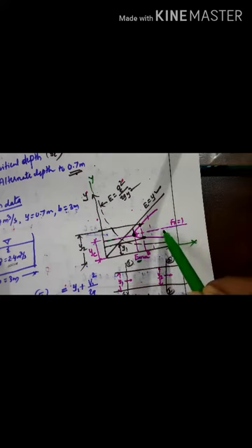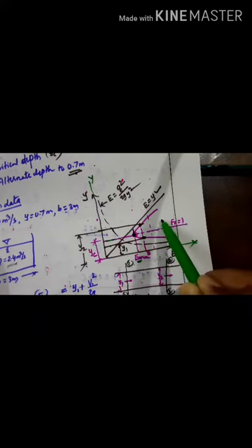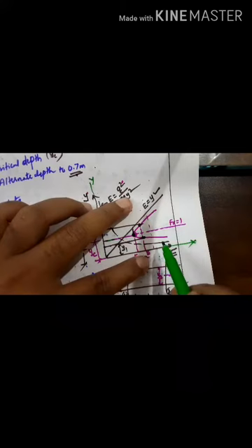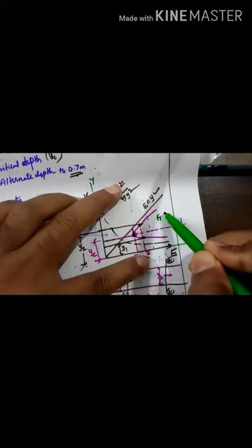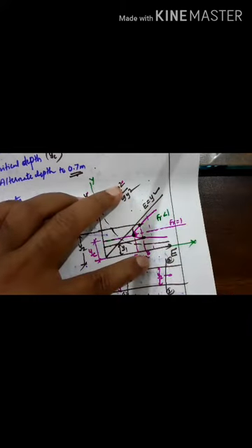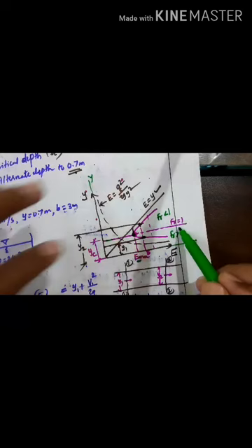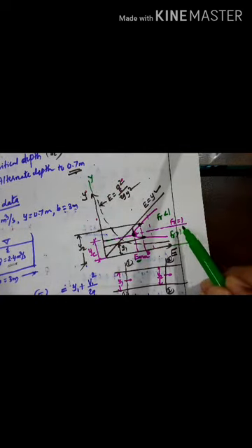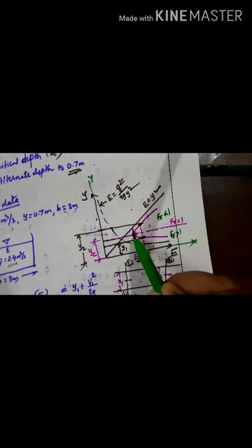Any depth above it shows subcritical flow, where the Froude number is less than 1; below critical, the Froude number is greater than 1; and at critical, the Froude number is 1. At the point where the slope is 0, the energy is minimum on that curve.